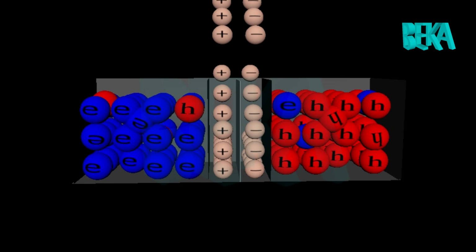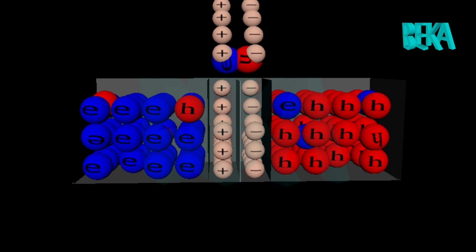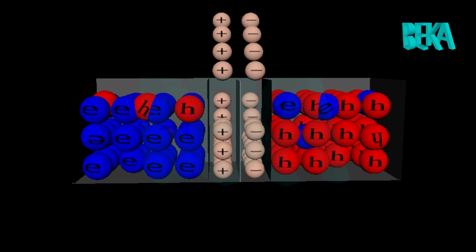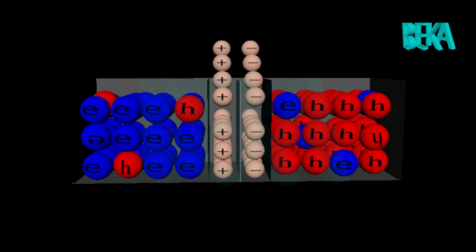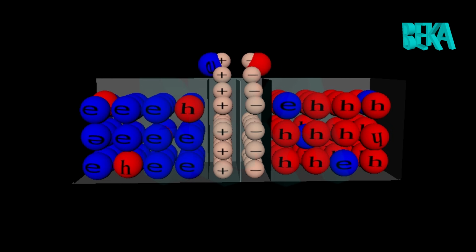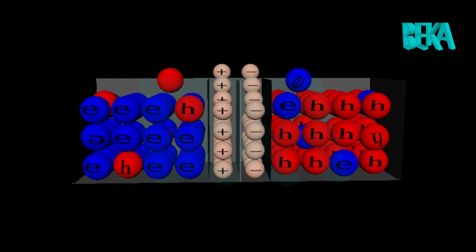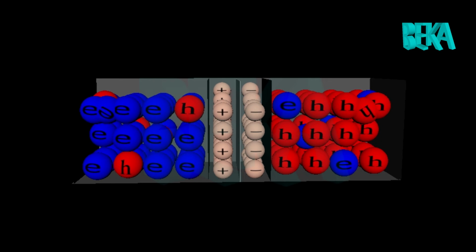As a result, the charge density of the p-type along the junction is filled with negatively charged acceptor ions, and the charge density of the N-type along the junction becomes positive. This charge transfer of electrons and holes across the p-n junction is known as diffusion. This process continues back and forth until the number of electrons which have crossed the junction have a large enough electrical charge to repel or prevent any more charge carriers from crossing over the junction.